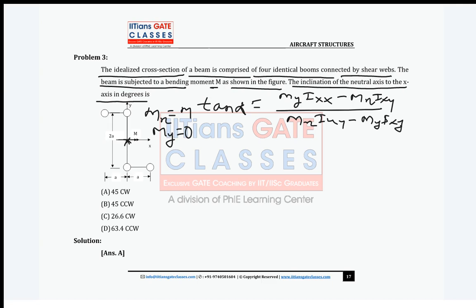Now substitute My is 0. So what will be your tan alpha? It will be minus Ixy upon Iyy, right?